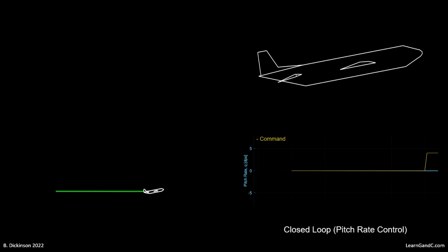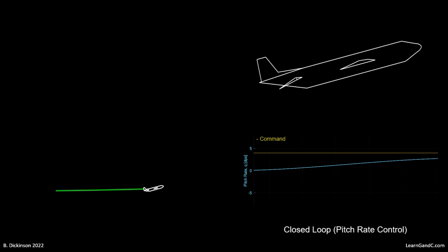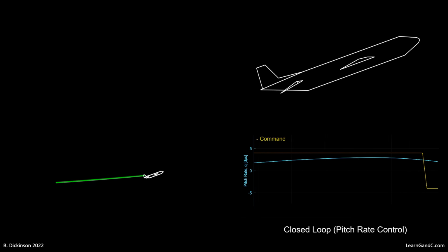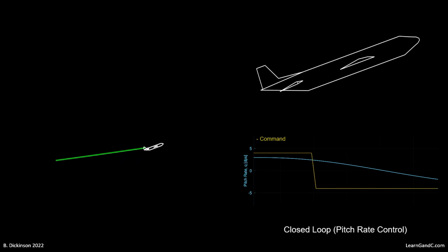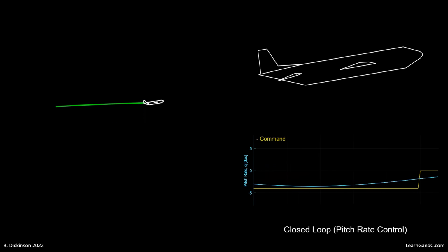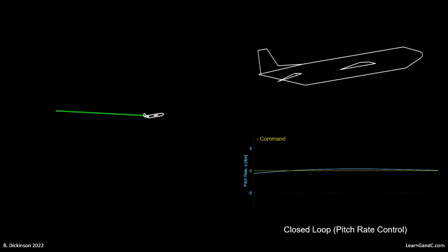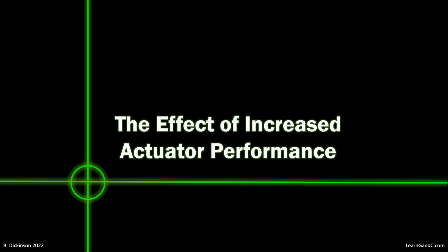Animating the pitch rate doublet, notice the gradual change in elevator motion consistent with its eigenvalue of -1, or approximately 0.16 Hertz, an unrealistically slow actuation system. But many lessons are to be learned in going through the exercise. Now, let's assess the controller for a more realistic, faster control actuation system.